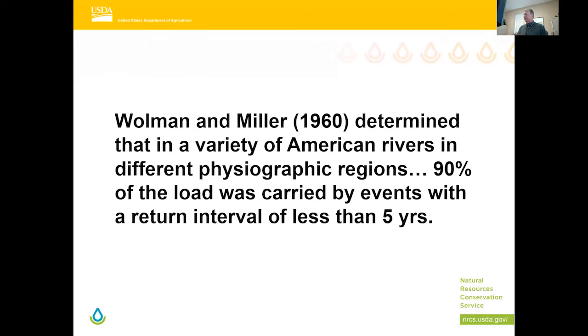So it's not those 100-year storms or 25-year storms that are causing the shape and effect of the channel overall. They may temporarily relocate parts of it or have some effect on them, but in general, the sediment and other types of things are carried by smaller events, anywhere from the 1 to 5 year storm or flow event in the channel.